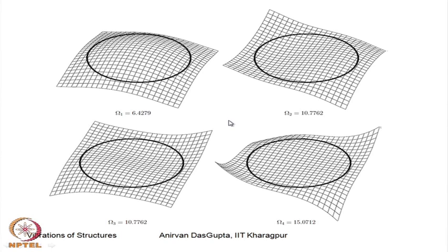As you can see, this is nothing but a rotation of pi by 2, which is the symmetry of this problem, because this is a square plate. Rotation of pi by 2 is not going to change the problem. So, you can see that this mode is a rotated version of this mode and vice versa. Then this is the third distinct mode. The second mode is degenerate.